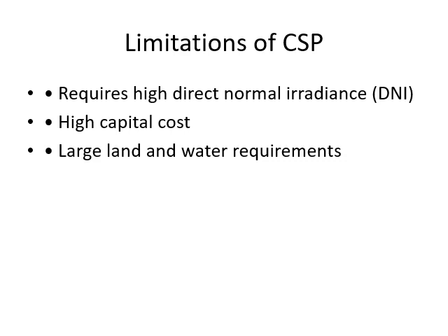Definitely CSP is dependent very much on the high direct normal irradiance, DNI. It is not that efficient in capturing the diffused irradiation. It does give some improvement in zones like tropical areas where the diffused solar irradiation is higher, but it is mostly dedicated for high direct normal irradiance concentration, and it will require large land and water. Definitely with high temperature, to cool it off or use it, we need water. Plus if you're setting up the heliostat system, it will require large land.